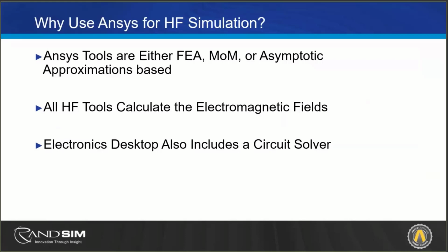Lumped parameter models are really good and really effective at lower frequencies. But as you get into these high frequencies, these gigahertz, these terahertz range, they really begin to break down. And having a field solver simulation tool is extremely important.